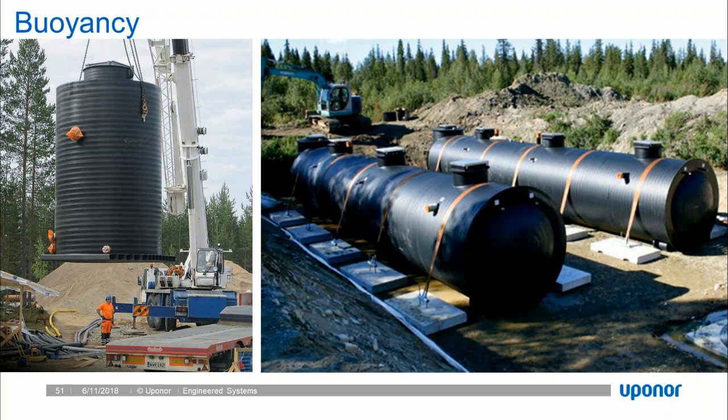Typically 5% of the downward force is due to the weight. The other 95% is due to the soil column's load distributed on whatever horizontal projection we can create. So for vertical vessels, we expand the footprint. And for horizontal vessels, we want to expand the footprint as well to capture more soil under the structure.